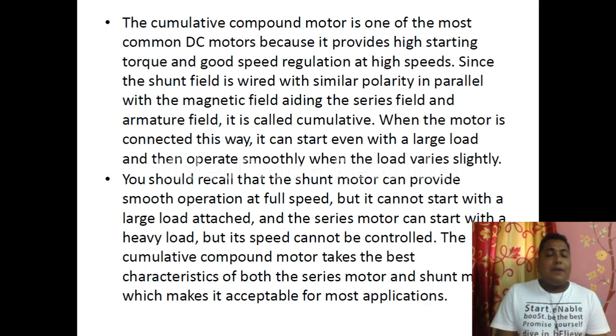Clear why it is called cumulative? When the motor is connected in this way, it can start even with a large load and then operate smoothly when the load varies slightly. You should recall that the shunt motor can provide smooth operation at full speed, but it cannot start with a large load attached, and the series motor can start with a heavy load, but its speed cannot be controlled.